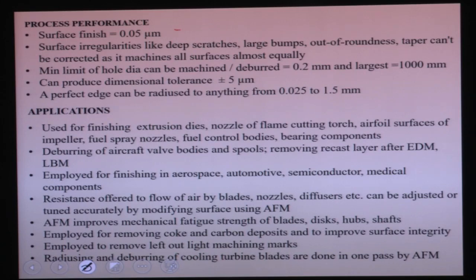Applications: used for finishing extrusion dies, nozzles of flame cutting torches, aerofoil surfaces of impellers, fuel spray nozzles, fuel control bodies, bearing components, deburring of aircraft valve bodies, spools, and removing the recast layer after EDM and LBM. Employed for finishing in aerospace, automobile, semiconductor and medical components. Resistance offered to the flow of air by blades, nozzles, diffusers, etc. can be adjusted or tuned accurately by modifying the surface using the AFM process.